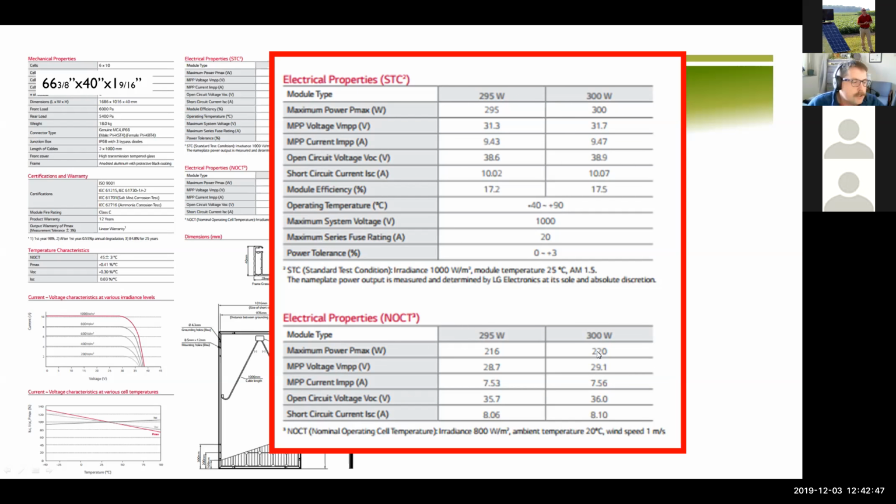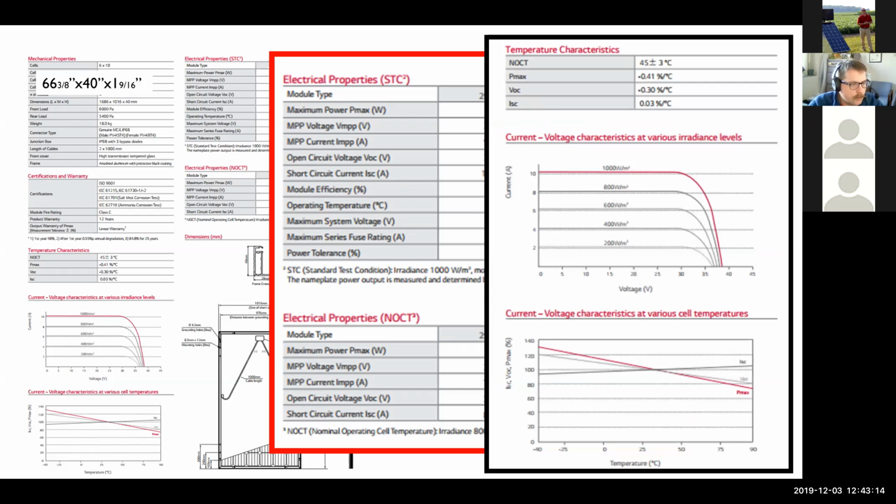So we just need to recognize that when we're talking about it, we almost always label it under standard test conditions, but that's not the way it really works. It's actually going to be less than that. And we base our actual calculations either on the real world numbers that they provide, or we make our own real world numbers, or the models do it for us. So we ought to be careful not to think it'll ever produce what it would in the lab, because real world conditions are always less.